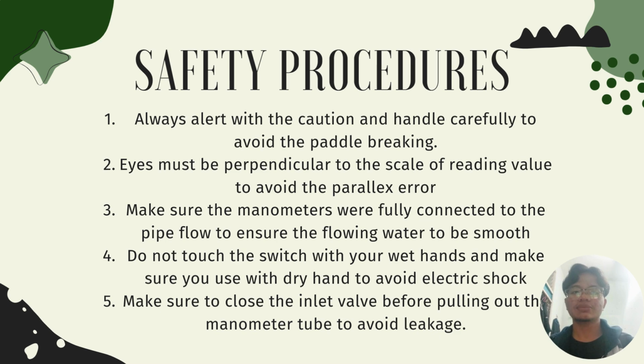Second, eyes must be perpendicular to the scale when reading values to avoid parallax error. Third, make sure the manometers are fully connected to the pipe flow to ensure the water flows smoothly. Fourth, do not touch the switch with your wet hand, and make sure you use a dry hand to avoid electric shock.